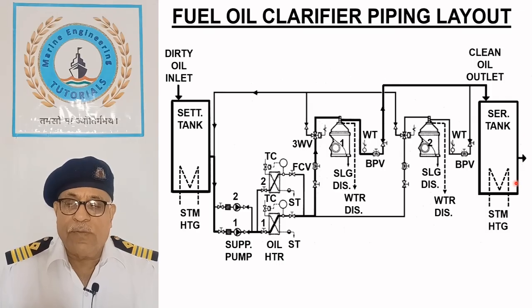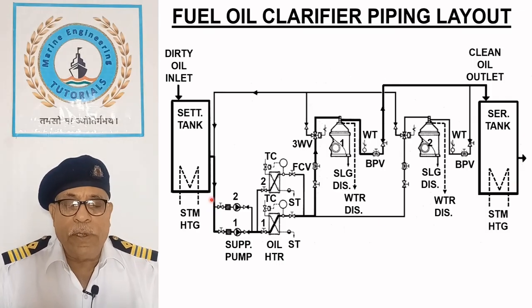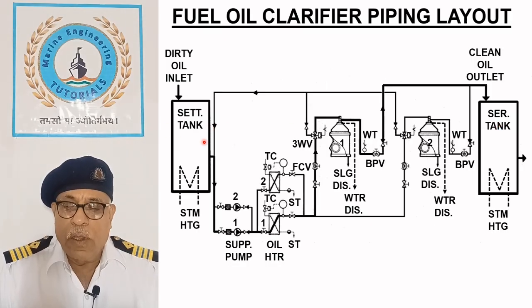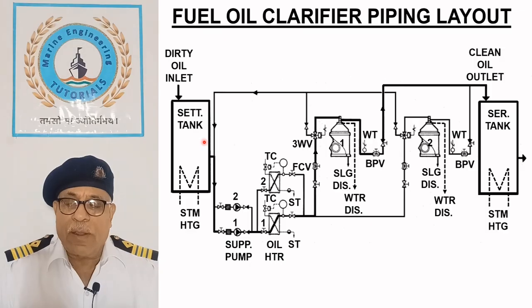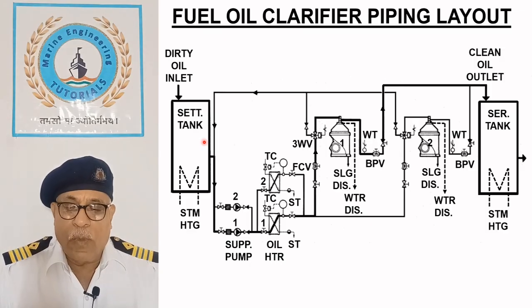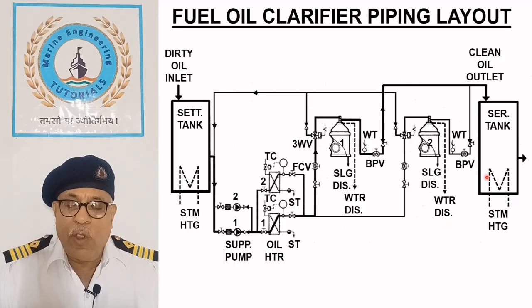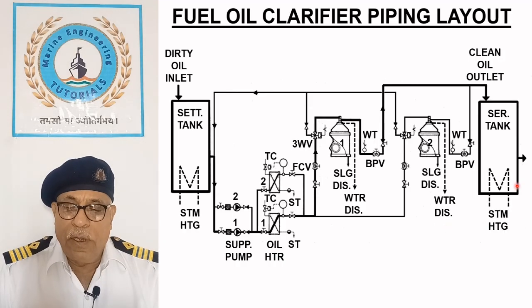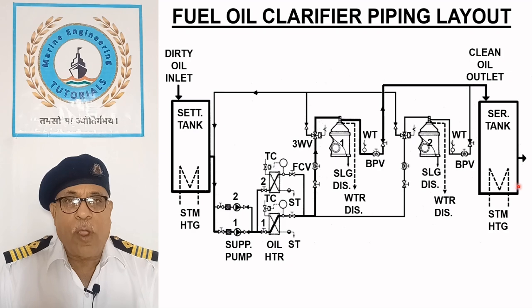The settling and service tanks are located side by side so that excess oil from service tank can overflow back to settling tank, keeping the service tank always full. When necessary, purified heavy oil is reheated by the steam heating coil.